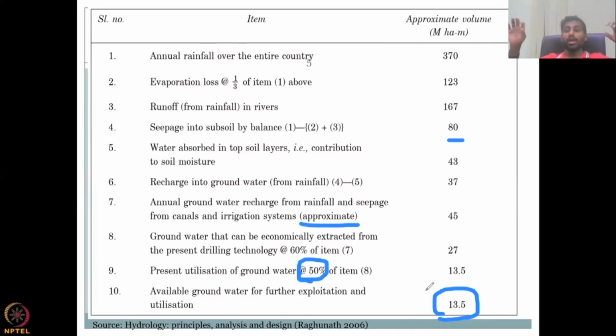and then they've written it down, identified which are the key parameters and thrown out the negligible parameters like ET, water capture in the canopy, those kind of things through rainfall, etc. They leave them out. We don't know, we don't want to. And then they put estimates for each and every parameter, 1/3, 50%, 60%, and then arrive at recharge. So this is another way of estimating groundwater recharge.